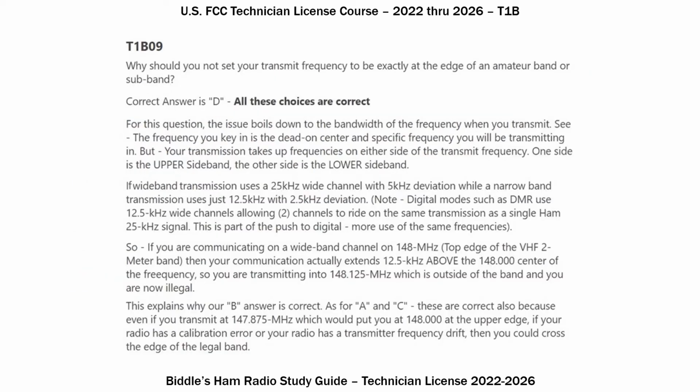Okay, this is a little bit more drawn out of an answer, but for this question, the issue boils down to the bandwidth of the frequency when you transmit. See, the frequency you key in is the dead-on center and specific frequency you will be transmitting in. But your transmission takes up frequencies on either side of the transmit central frequency.